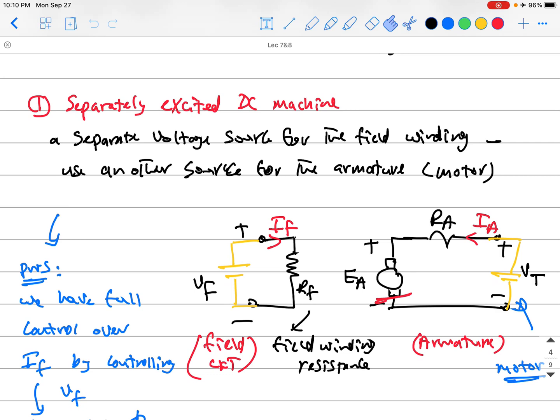So you have another set of winding in the stator to produce a magnetic field, besides the primary set of winding, which is the rotor, the armature winding, where your energy conversion happens. The other set of winding on the stator has the job of producing the magnetic field you need as a medium for energy conversion. So it's another set of winding that also needs to be supplied by electric voltage to pass electric current into it to create the required magnetic field.